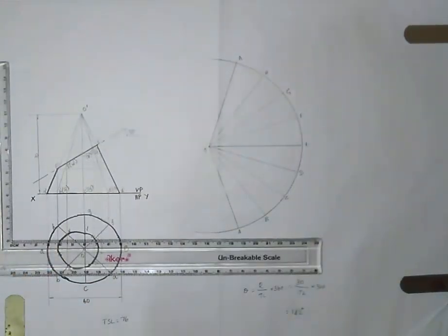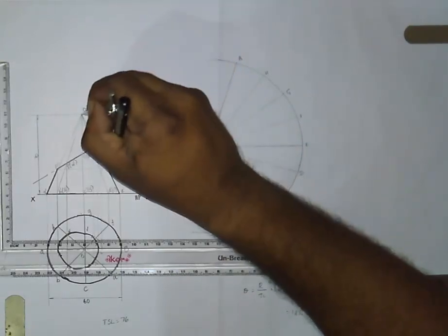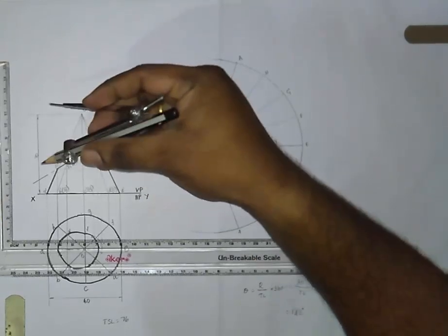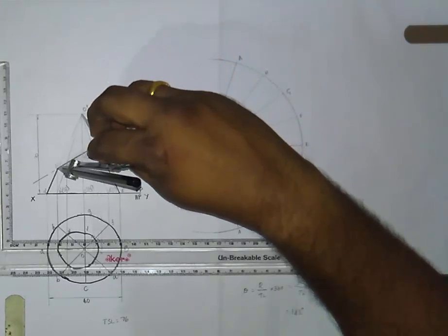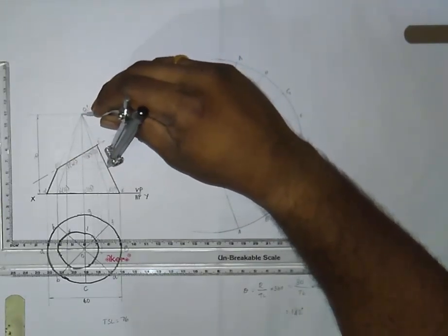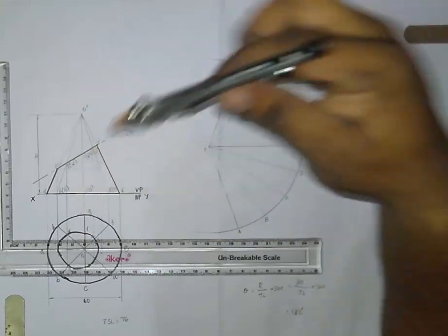Now take your compass, measure the point P from point O like this. This is your projected point P. You can make the point directly from here, since the line OA is also the true slant length, but without confusion you just measure it here, and the point P has to be transferred to the line OA.